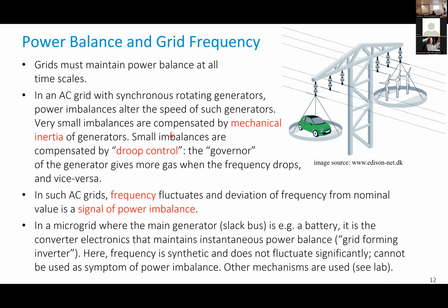For a nuclear plant, for example, it means that we release some vapor into the air to reduce the power a bit. So we never use 100% of the mechanical power of the nuclear plant. We use perhaps 95% of it, and we keep a few percent as flexible energy that we can throw out into the air or use in order to provide this balancing effect.